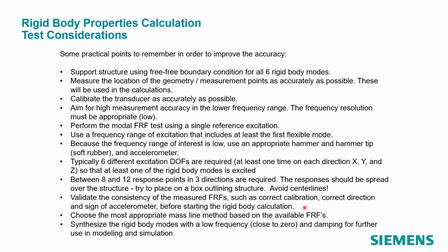If your modes are highly complex, so if they've got high phase scatter, and if they're highly nonlinear, this tool is probably not going to work that well. So again, do some modal validation checks and make sure mass sensitivity is proper, and make sure that the modes are fairly collinear.